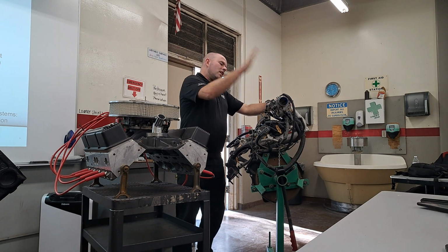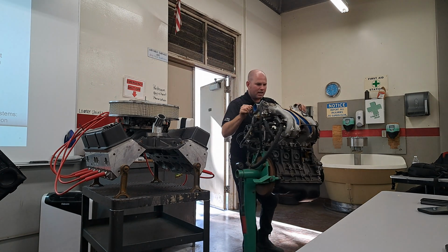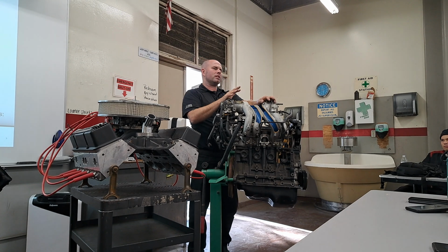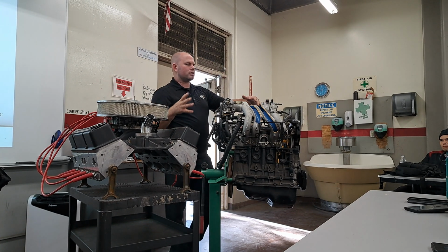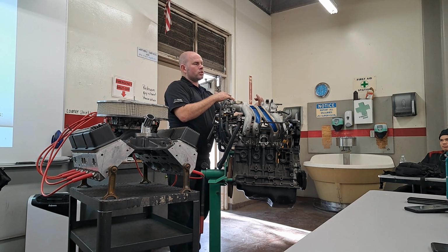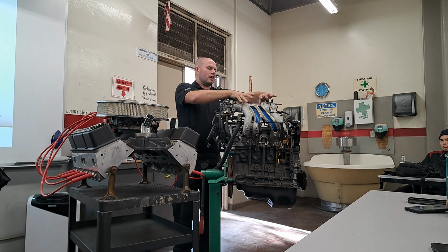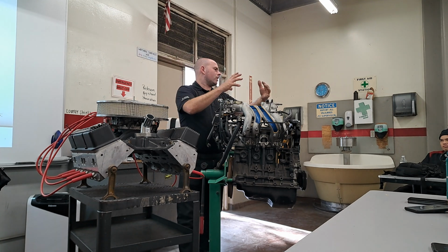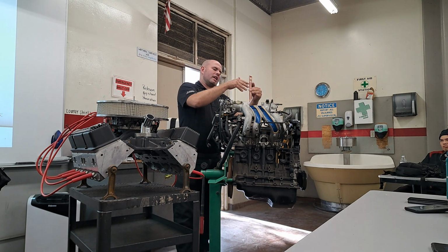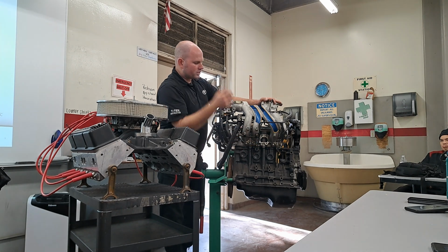And so it goes past the throttle, goes into the manifold here, which you can see in blue. Now let's define what a manifold is. Generally, a manifold brings multiple chambers into one or one into multiple. So in this case, one throttle body goes to this big top part that's open. We call it the plenum. That's sort of the gathering area of the air. Then it splits 4 ways and goes down into your 4 cylinders.